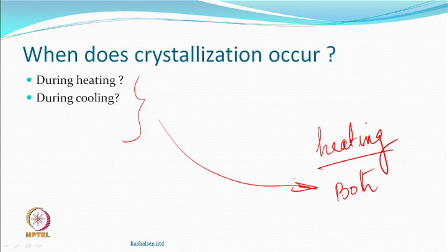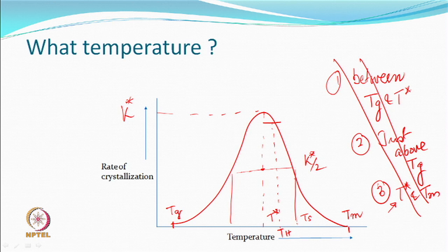During heating, decrystallization also takes place. Did we say that? You have to do partial melting. So, it does not mean that crystallization is not taking place. There is melting happening and there may be recrystallization also happening. This curve is wide and the melting is not taking place at one particular temperature only; it may start before. Smaller entities are melting, it is not the whole fiber that is melted, because when all the crystallites melt, it is melt.